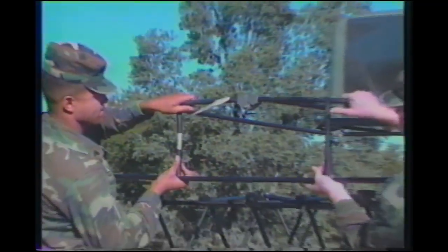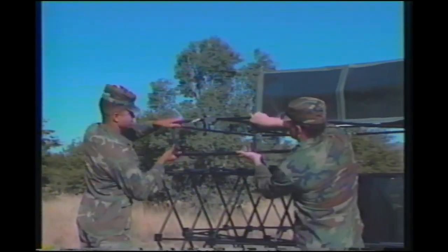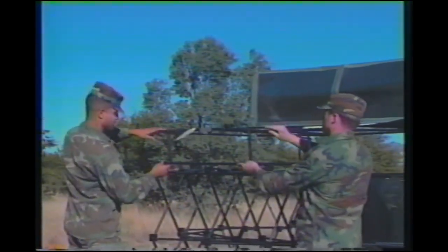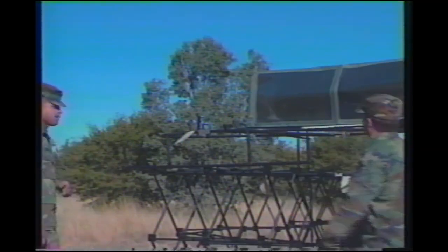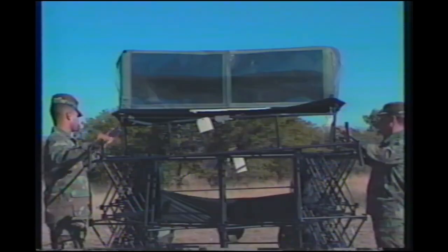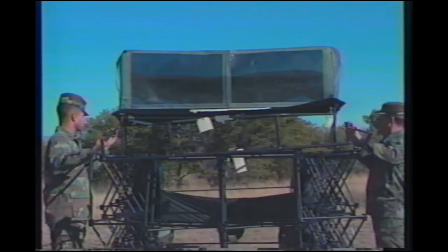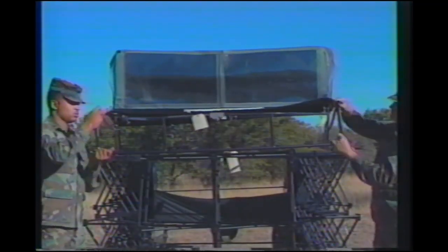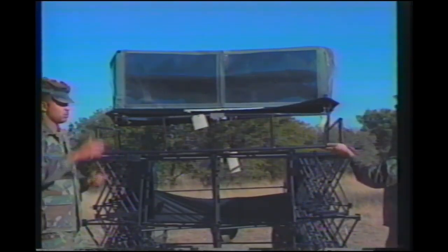Attach the lower front hood support L bars to each end of the lower front hood support bar by sliding over the ends of the bar. Allow the lower front hood support bar with L bars to rest on the top of the front frame. Attach the left and right side hood support bars to the windshield support bow. Insert the ends of the lower front hood support bar into the front end of the side hood support bars.